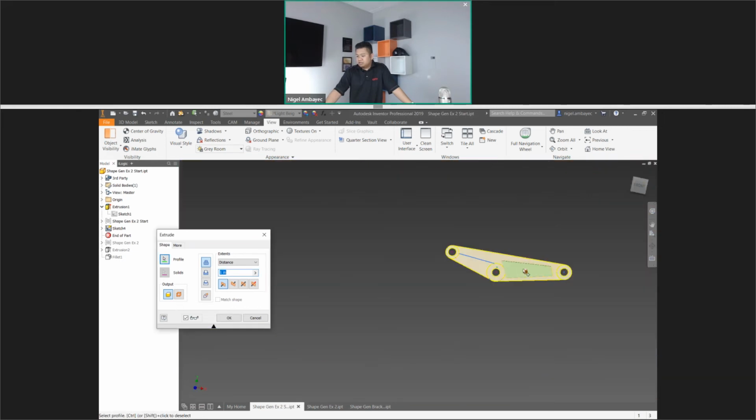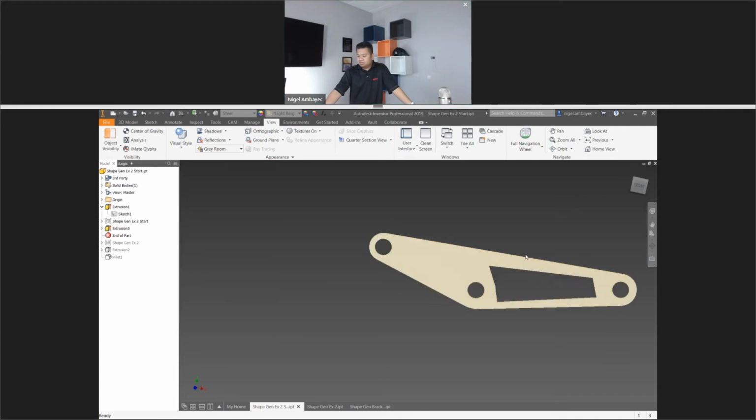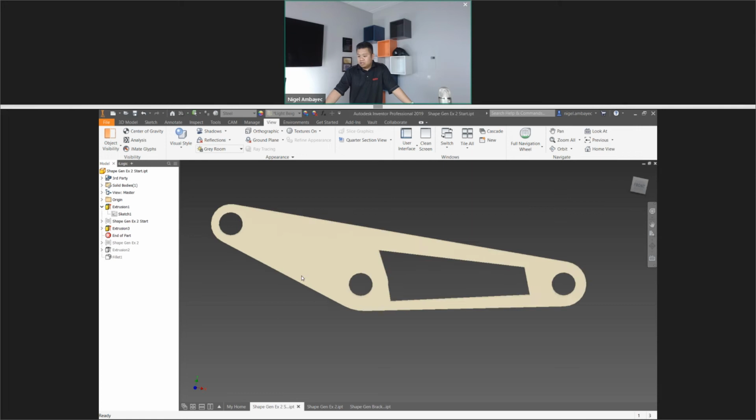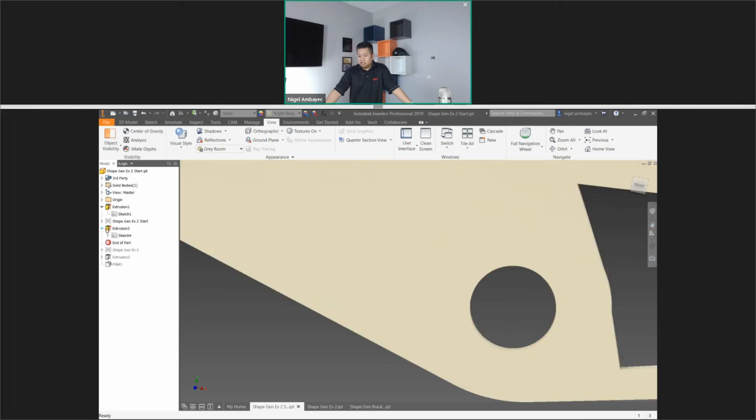So I can get rid of this region for sure, but we'll go ahead and edit this sketch so we can get rid of that. And we're going to do both directions, and we're going to do a through all. It's going to be an extrude cut. And then let's go ahead and edit the sketch so that we can get this part as well.